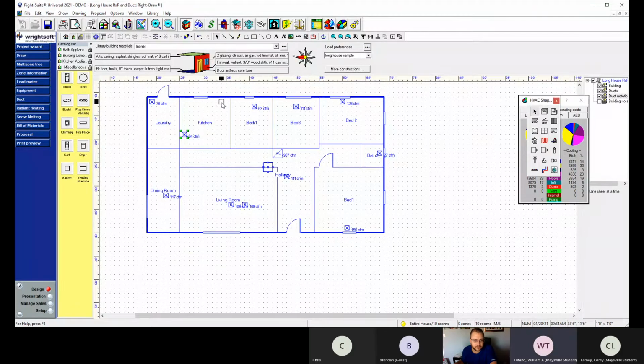Why do you want them under a window necessarily? Because people don't usually sit stuff in front of windows. Gotcha. And it provides a little bit more of a radiant barrier, with that cold air coming up and blowing in front of that window. So it might help knock down a little bit of that radiant heat that's coming through. But the practical reason is people don't sit stuff in front of windows near as much as they do in front of a blank wall space. So that's just kind of a trade rule of thumb, I guess.